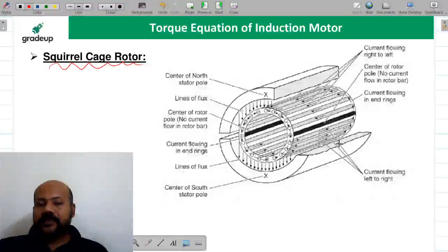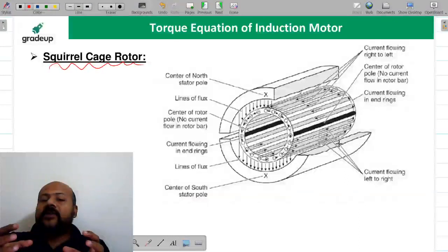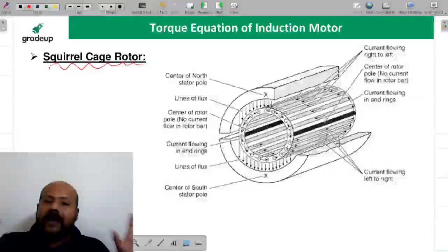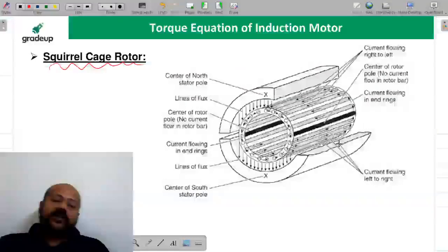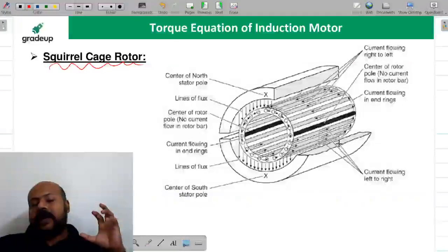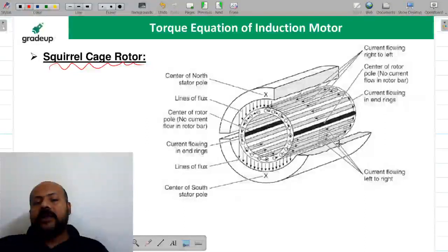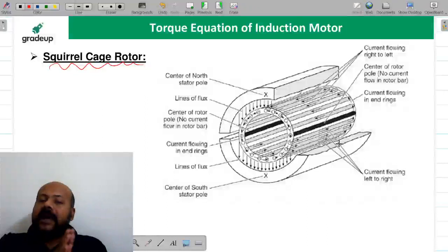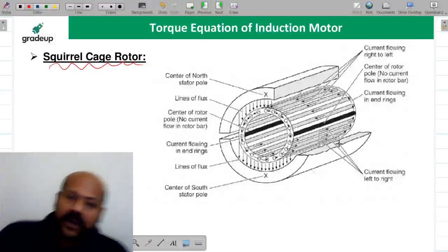Now you can understand that your induction motor is standing on only one leg, only single support it is having. Because it is a singly excited machine, all the responsibility is on the stator side, supply. Yes or no? So if it has to maintain a stable operation, the air gap between the stator and rotor periphery must be minimum as much as possible. I hope it is clear.